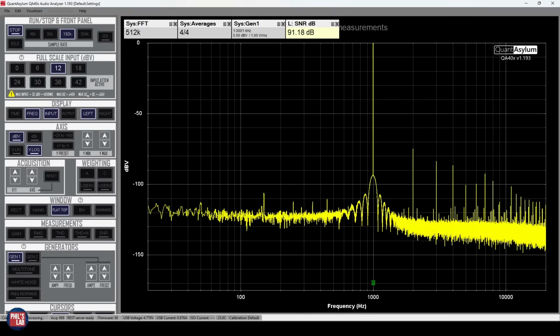and we can see we've increased the noise floor because now we have this distortion here as well, due to maybe clipping in certain stages or general distortion artifacts, which of course will increase the noise floor. So anything that isn't this 1 volt RMS signal is effectively noise. So this is what the system is now computing. It's computing the magnitude of the 1 volt RMS signal, our input 1 kilohertz signal, relative to everything else. And then it computes our signal to noise ratio to be just above 91 decibels, which is fairly okay.